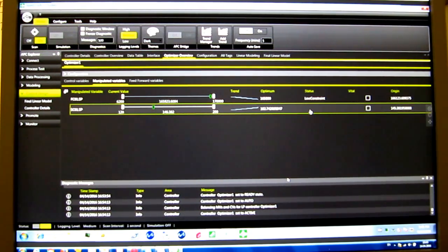So, in terms of technology comparison, this is where the APC technology brings most of the advantage, because a normal PID control, or probably an expert system based on rules or if-then-else kind of programming, will do the control part very similarly to what an APC solution can do, but they don't have the optimization component. So in this particular problem, what we are trying to do, for example for the ball mill, is to maximize the throughput, but at the lowest possible power consumption. So we are trying to solve